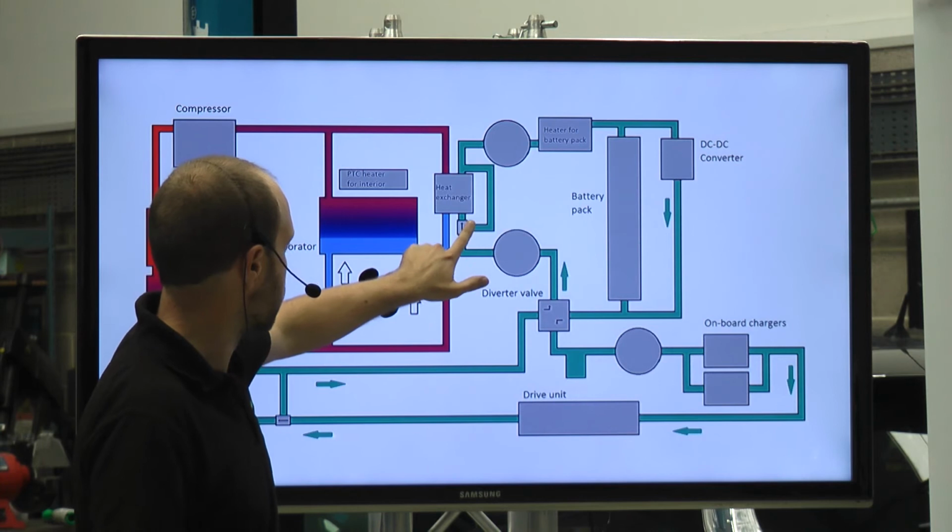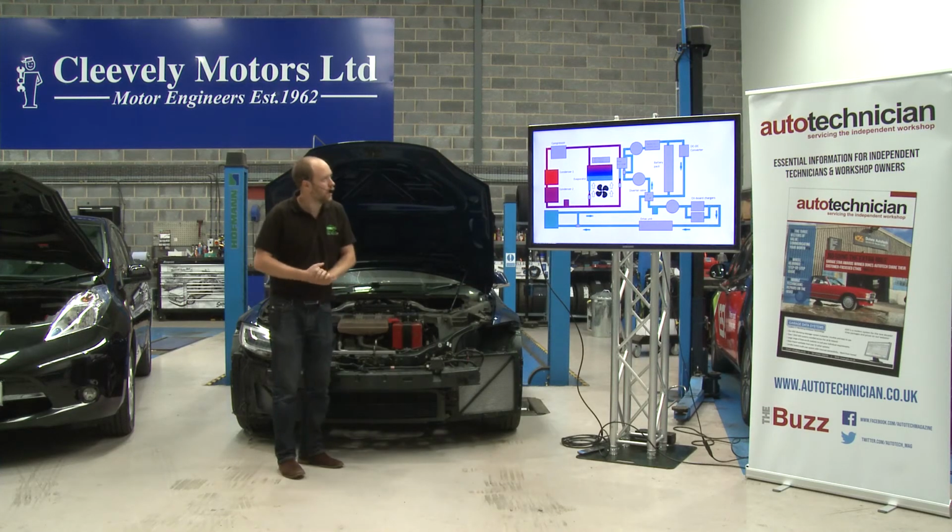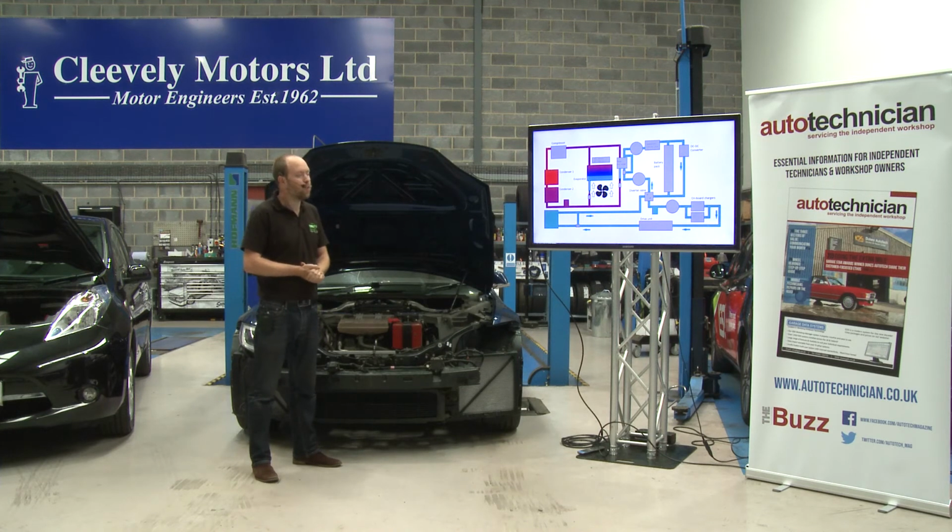So later cars like this, they've actually done away with that little branch of the circuit. So that's how they can use one relatively simple cooling circuit to cool the onboard electronics, warm the battery, and also cool the battery to colder than the atmospheric temperature if required.